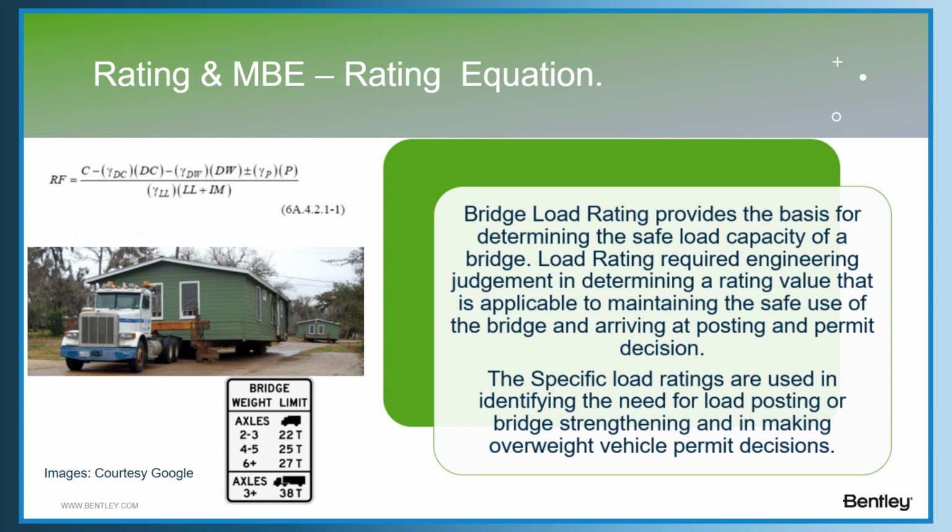So as per the Manual for Bridge Evaluation code, the rating factor equation has been provided in article 6A.4.2.1-1. The equation is pretty simple. It's the capacity minus the load factor times the dead load, divided by the load factor times the live load.